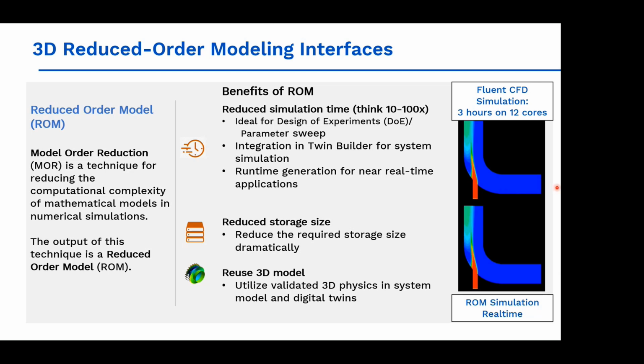In Fluent, if I run this case, which is a transient case, it will take over 3 hours on a 12-core system to complete. Now, from the case and data files that I generate over this 3 hours of time, I can capture snapshots of what will happen if the temperature is at 10 degrees, 20 degrees, 30 degrees, 40 degrees, 50 degrees, and then 100 degrees. I captured the final solution file for each of those input temperatures and then clubbed them together to form the reduced order model.